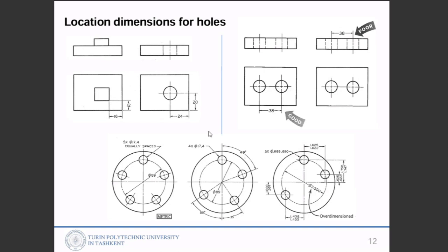And below you can see three types of definition of circular dimensions, positional dimensions of circles. On the left hand side, first we draw two vertical and horizontal center lines, and then by referring to this cross point center, we draw another circle using a chain line like this.